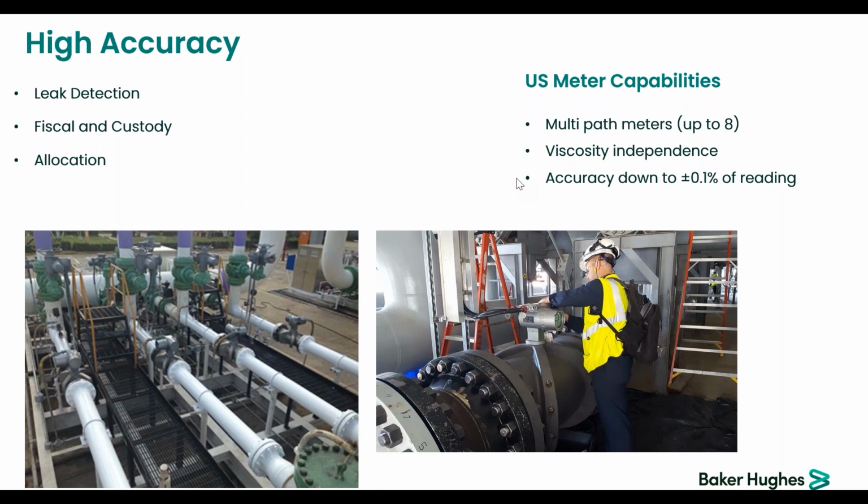So in other words, unless you have a regulatory requirement, there is no need for recalibration because the technology by itself is not prone to drift. But I would recommend that once in a while you look at the diagnostic parameters to ensure that none of them is outside the boundaries.